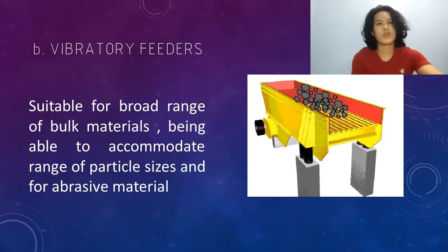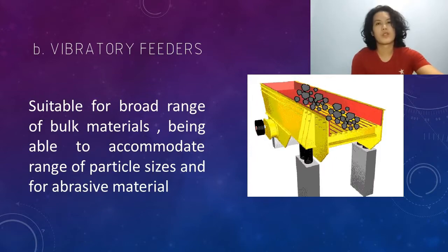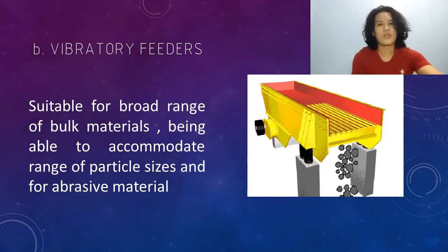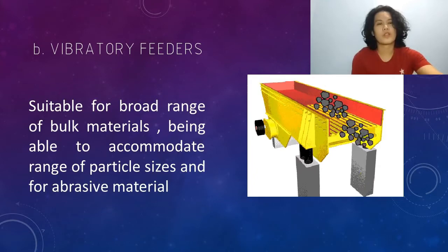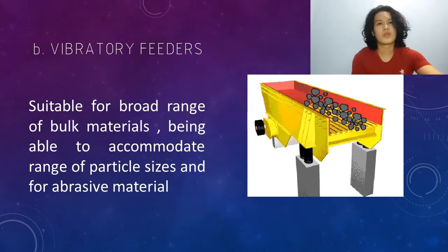When a screw conveyor works, the screw shaft rotates and the material moves forward along the trough bottom of the conveyor under the push of the blade. Because of gravity, the material, and the friction with the groove wall, the material does not rotate with the blade of the screw conveyor.